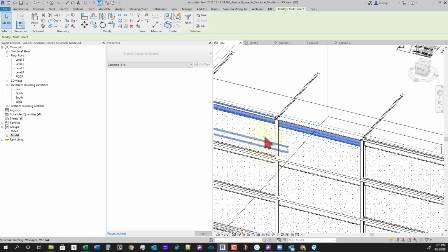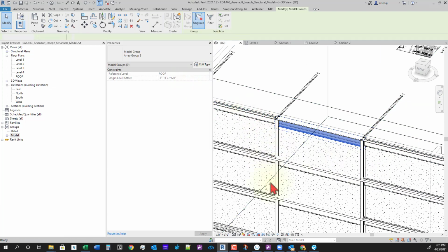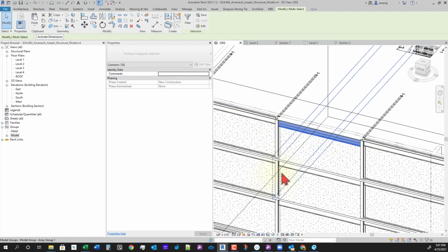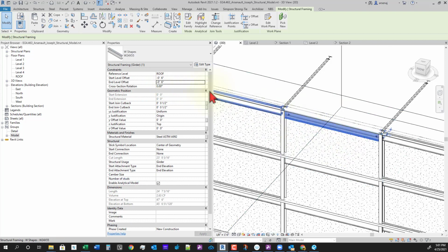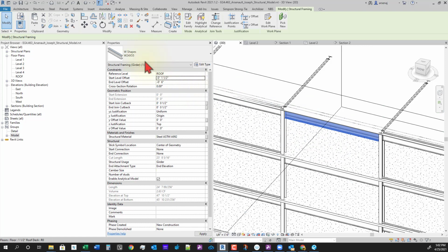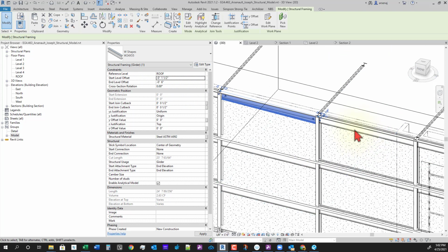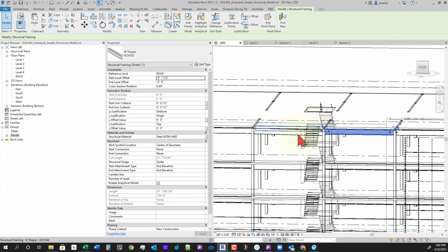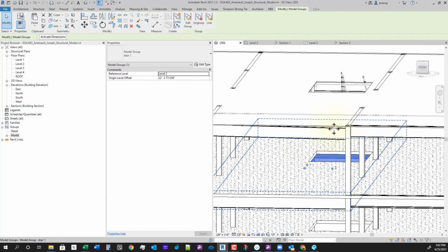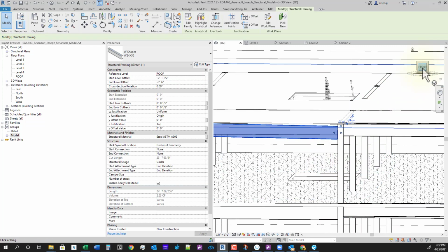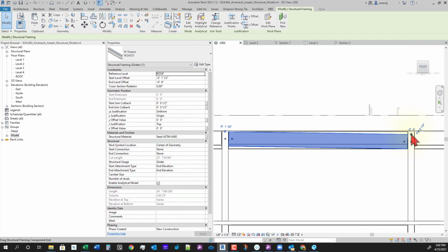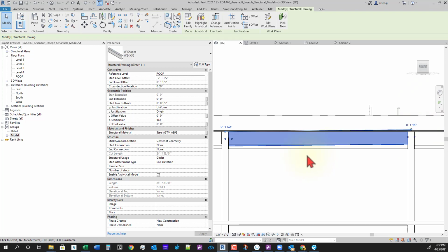Let's see. Yeah, just hit ungroup for all the ones that aren't arrays. And make sure that these ones at the roof are only -1.5 inches. And it looks like this beam is a little bit wonky. It's a little bit angled. So let's just, oh, it's because I only gave it one side 1.5 inches.